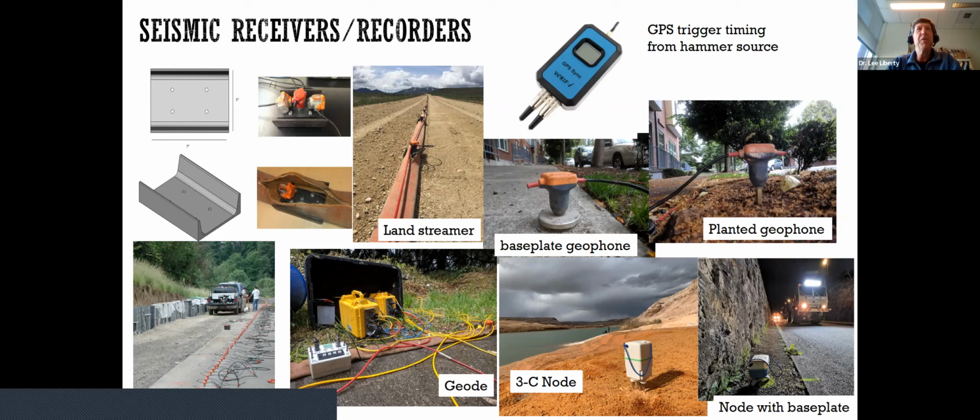We actually drilled into a sidewalk that was slated for demolition. Since then, we've started developing these land streamers, and land streamers have been around for a couple of decades now. I think the group out of ETH in Zurich, Alan Green's group, published the first results from land streamers back in 1999. So it's nothing new, but they really have become much more popular for operating on roads and the like, simply because you don't have to plant phones. It's significantly faster to deploy, and the data quality doesn't seem to suffer at all.